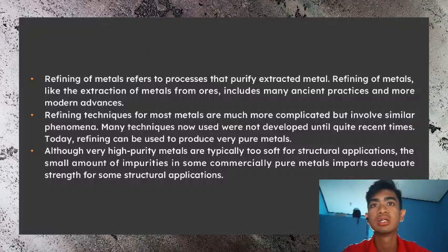For example, commercial heat exchangers for certain applications are made of commercially pure titanium. Although titanium is characterized by a somewhat low thermal conductivity, the major design factors in heat transfer relate to material thickness, corrosion resistance, and surface films, not just to the thermal conductivity of the metal.